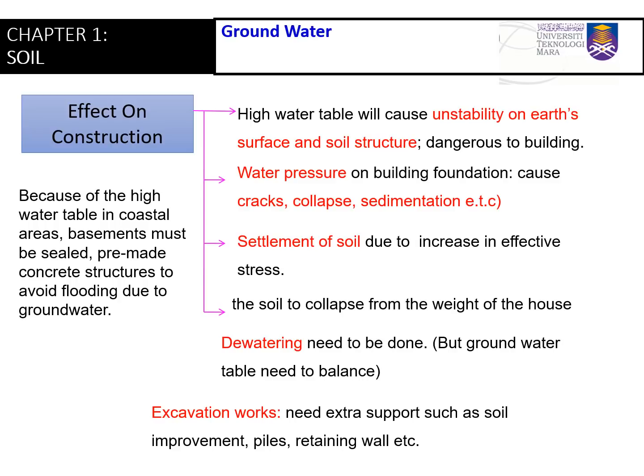So if you do not have proper drainage, these will cause high water table around your house. So go back and check your house whether the perimeter drain is proper or not. Otherwise, it can do harm to your building.